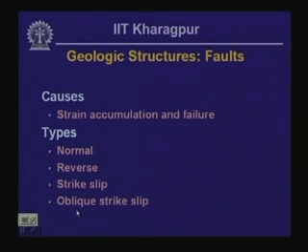What do we mean by fault? As illustrated in the last sketch, rock masses are crisscrossed by joints; there are different blocks of rocks underneath a particular site. Now, these blocks sometimes try to move relative to each other. That could be because of several different things: again because of stress regime change, or because of intrusion, or because of seismic activity in a nearby location.